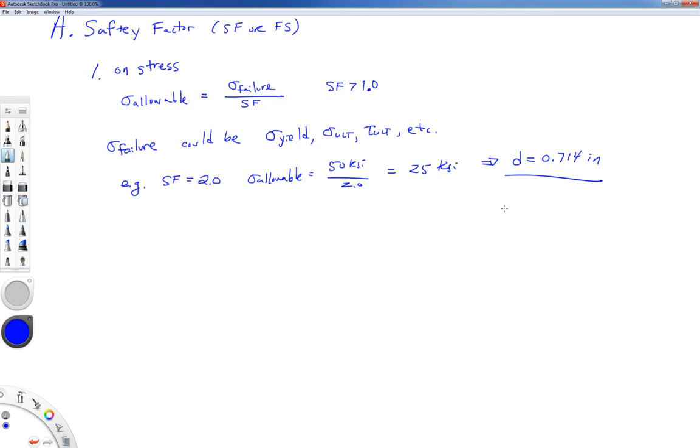So for an example, a structure like a bridge, you may have a safety factor that might be 3 or 4 on particular components of that kind of bridge. It's a large piece of civil infrastructure. It lasts a long time, maybe 50 years or more before it gets replaced, and the loads may change on that over time. Truck loads may be increased, traffic levels may go up, so you don't really know exactly what's going to happen so many years in the future.